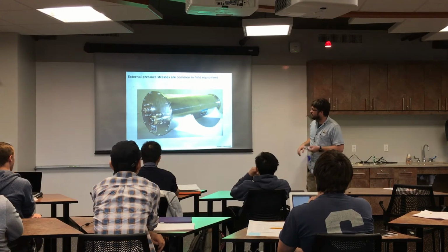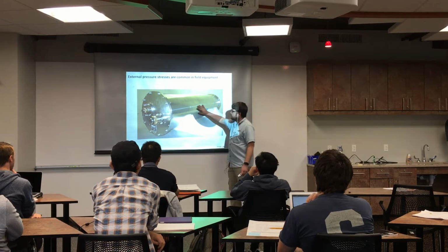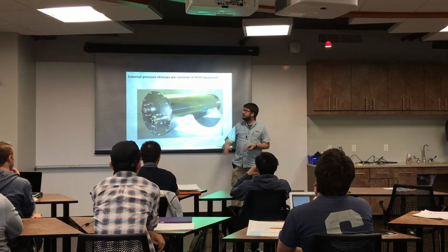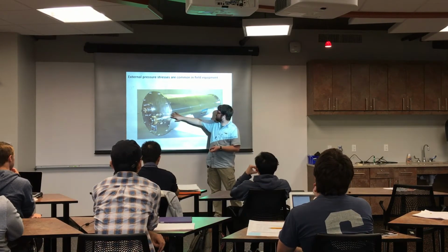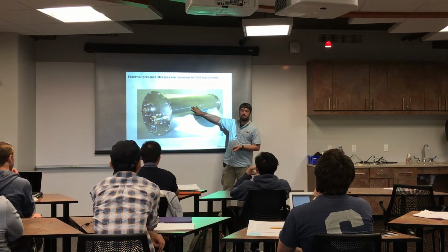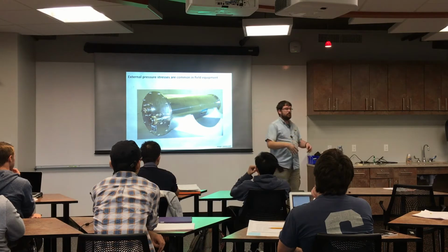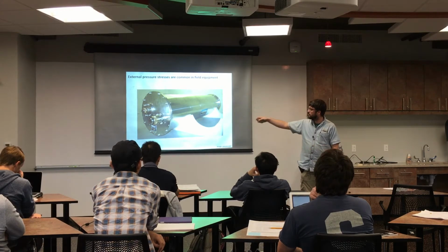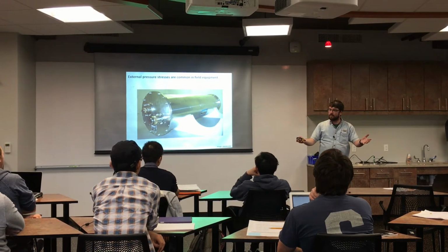Another common practice with these is, if the equipment inside can take some pressure, but not the pressure that you're going to be at depth, let's say you're at 250 meters water depth, which is 400-ish PSI, then you could fill this with oil and have oil support part of the load from the water. So the vessel wouldn't have to be quite as strong. But then whatever's in the oil needs to be able to support part of the load as well. Make sense? You'll also often see pressure vessels having domed ends.